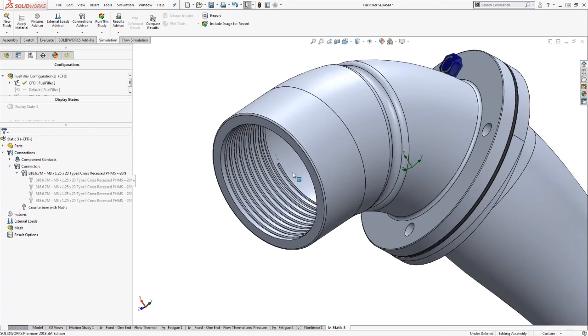Right? And you see that there are a lot of thin walls there. Really the concern here is the mesh, trying to mesh those thin edges. You want to get a good resolution, and ultimately all you want to say is it's restrained within that model. So we can get rid of those threads, add a split line, add a split face within that region, and just fix that face.